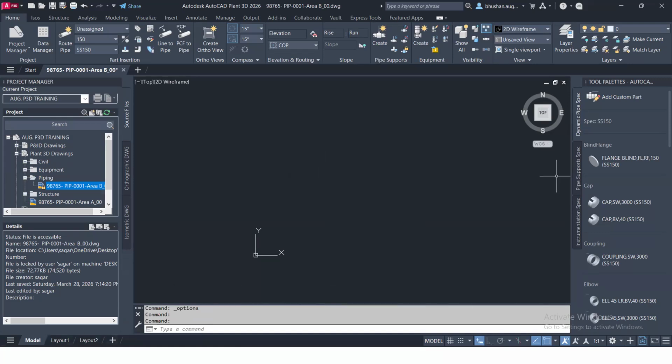Okay. So in real life, a pipe is not just a pipe. It has a nominal diameter, like size, a wall thickness, a material like carbon steel, stainless steel, etc., a pressure rating, how much pressure it can handle, a temperature rating. In a process plant, the engineering team creates a document called a piping material specification, or simply the pipe spec, which defines what kind of pipe, elbows, flanges, etc. to use for a particular service.